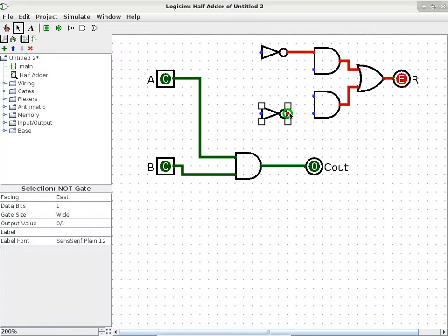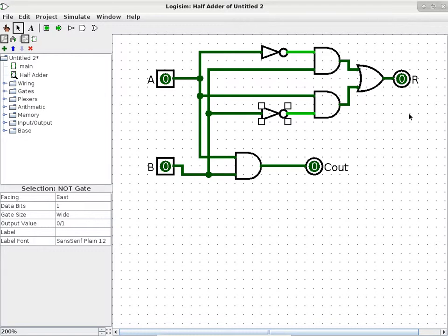All right, so now we'll use A to feed into this negation here, and A non-negated feeds directly into the conjunction here. This one is going to be B non-negated, so we'll put it down here, and the other one is going to be B negated. All right, so I think I got the half adder done already.